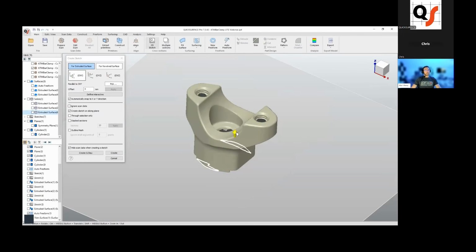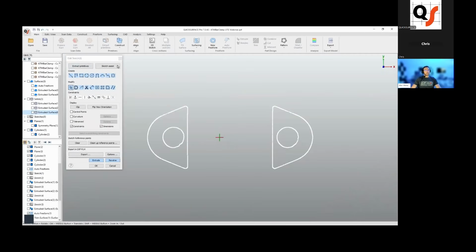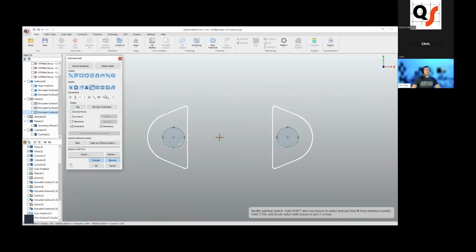So once again, we'll just create a 2D sketch, go up to roughly where those holes are, and extract those primitives. So I'm going to go ahead and, again, hold down Alt. Anywhere there's a big discrepancy, go ahead and grab that. This one looks pretty good, so I'll grab that. Another thing that you may want to do, again, is give these dimensions. So I know this is 7, we'll do 7 millimeters for each of these.